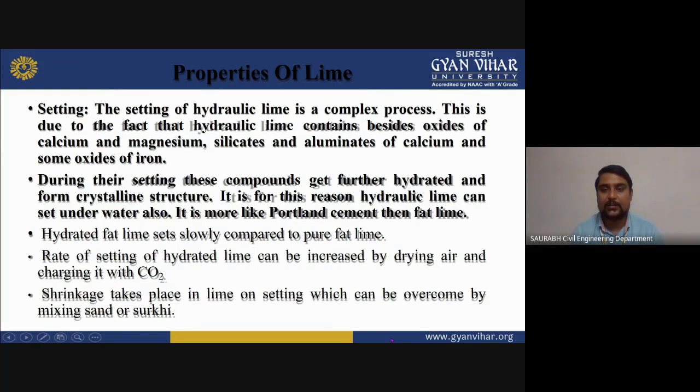And the setting of hydraulic lime is a complex process. This is due to the fact that hydraulic lime contains, besides oxides of calcium and magnesium, silicates and aluminates of calcium, and some oxide of iron. During their setting, these compounds get further hydrated and form a crystalline structure.